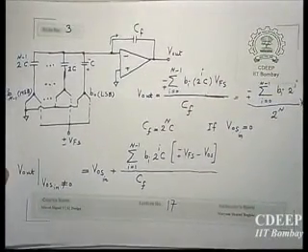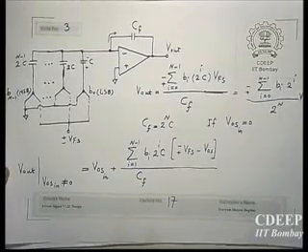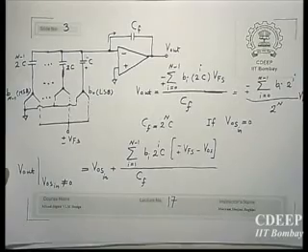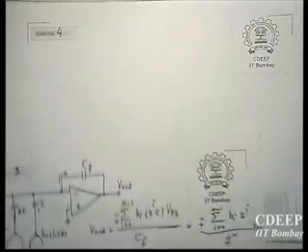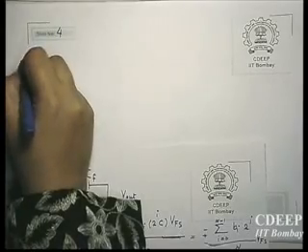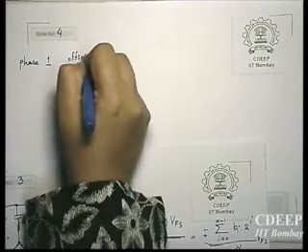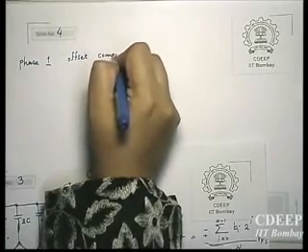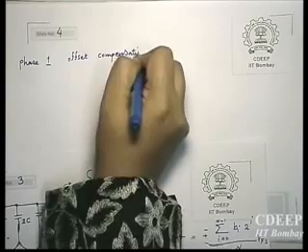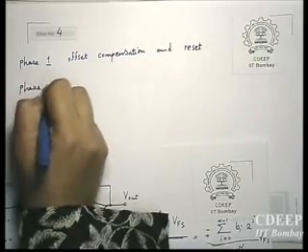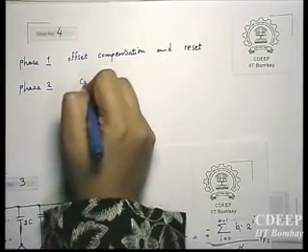So to do that, we need to have a two-phase conversion. Okay, so this was a parallel conversion. It seems in one phase it can be done. But we need to put one phase for offset compensation. Therefore we will have two phases. Phase 1 for offset compensation and reset, and phase 2 for conversion.